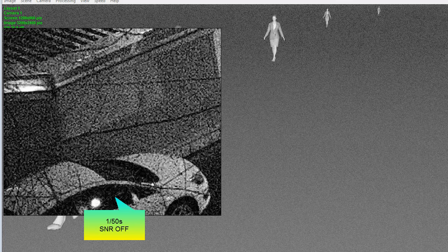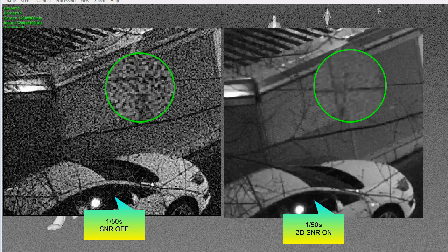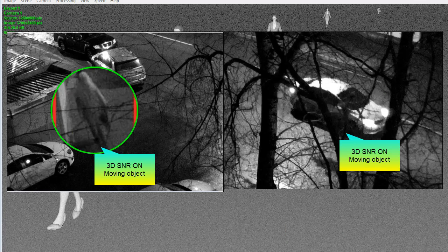With modern cameras, the noise is visible only when the noise reduction system is switched off and the gain is increased. In normal mode, the noise is effectively suppressed by the noise reduction system. But we must remember that the 3D noise reduction improves image quality of motionless objects only. Images of moving objects do not increase quality and become blurred. These distortions are less noticeable than the noise, but moving objects usually are of greatest interest.